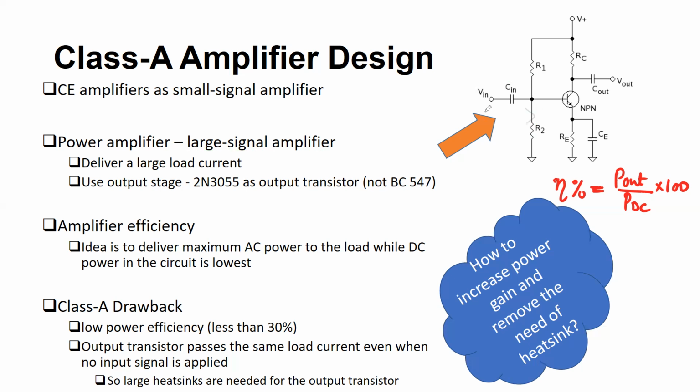With a small signal amplifier, you have an input and an amplified output, inverted though. Your output power, the product of voltage and current, is in the range of microwatts, or less than, let's say, 1 milliwatt. That's the definition of using this circuit as a small signal amplifier.